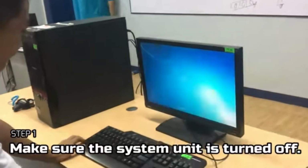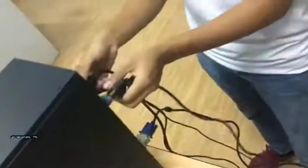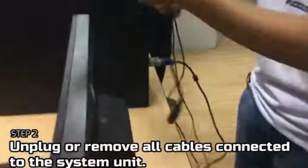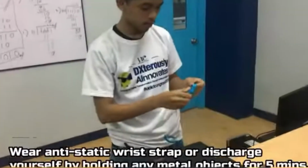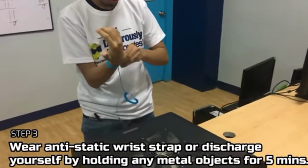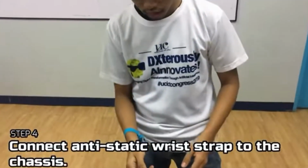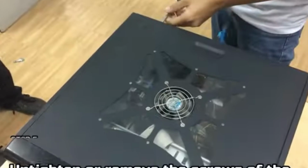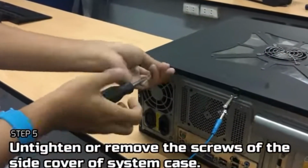Step 1. Make sure the system unit is turned off. Step 2. Unplug or remove all cables connected to the system unit. Wear an anti-static wrist strap or discharge yourself by holding any metal objects for 5 minutes. Connect the anti-static wrist strap to the chassis and tighten or remove the screws of the side cover of the system case.